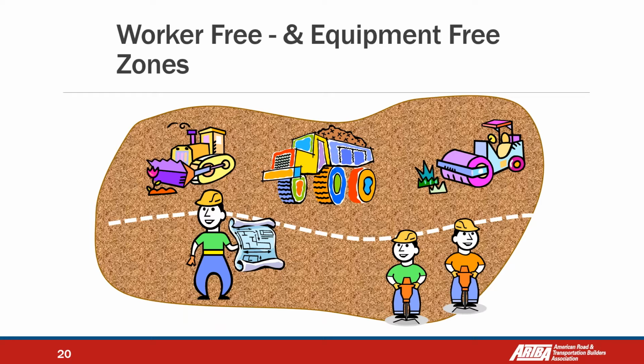Look, this is the main principle or the main idea of an internal traffic control plan: how to separate workers on foot from heavy equipment. If we create a plan with this goal, we are going to have maybe 90% of the plan done. This is the main goal, separating workers on foot from heavy equipment as much as possible by creating special areas for workers on foot and heavy equipment, and sometimes using some positive devices like cones and barrel signs to separate the areas.